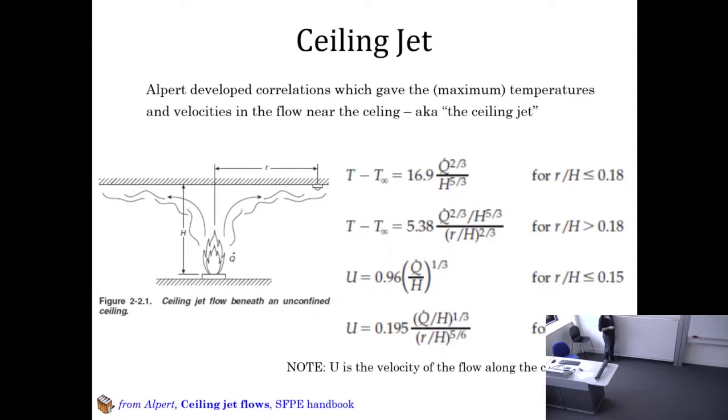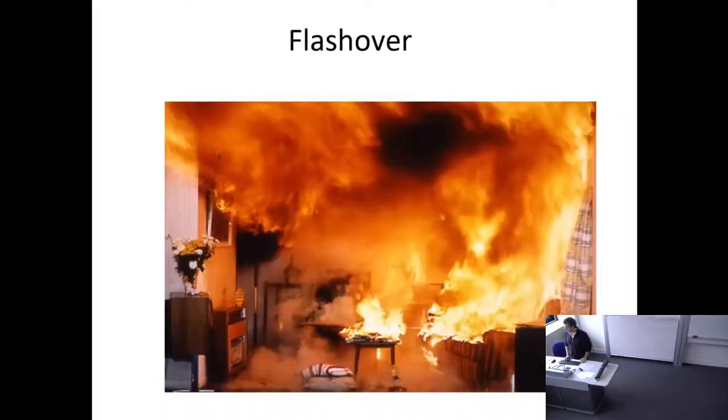As you put the sprinkler farther and farther and farther, you can see by this law that the temperature starts to drop. And the sprinkler has a critical temperature for activation. If it's over here and it's too far away from the fire, it might never be ignited. Sorry, not ignited. It might never be activated by the fire. Obviously, if it's right above, hopefully it will be. But the spacing of the sprinklers is critical, in that it has to be activated and still be within reach of the fire that it is trying to suppress.